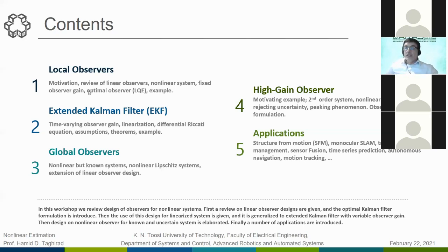In the morning, what we covered was basically the concept of how an observer works. We started with a linear system and linear observer, LQE design, and the Kalman filter, Kalman-Bucy filter in the continuous time domain. Then we extended the knowledge of the linear observer to some nonlinear cases with the linearization method. In this meeting, we talk about the global observer.